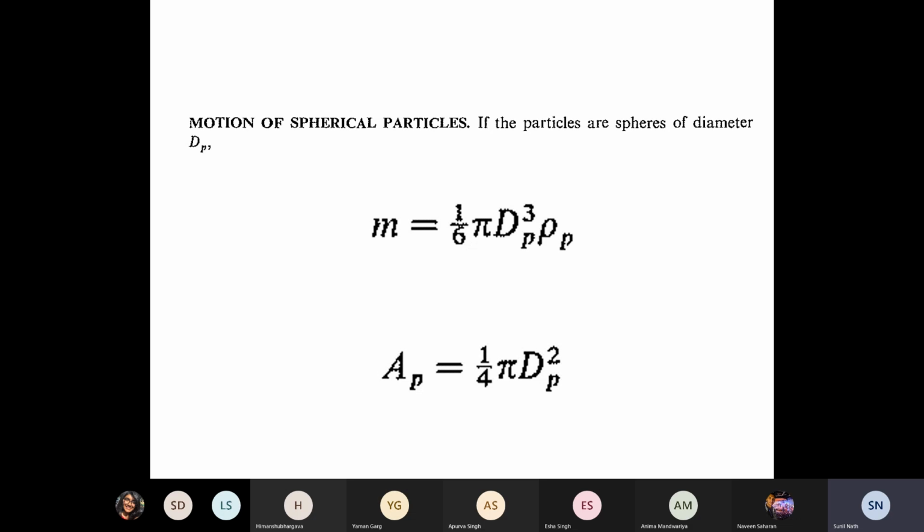And that we want to finish next time, and then we can worry about going to more than one particle, for which, as I said, there is no perfect theory, but what we can get can be done, and then there are applications in filtration where we take up Darcy's law type of things for several particles that are interacting with each other, and it is a constitutive equation. We don't have a perfect theory, but for a single particle we do have a perfect theory, right? That's what we will try to complete next week.